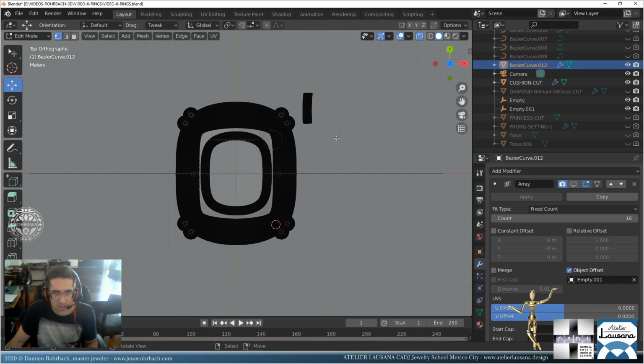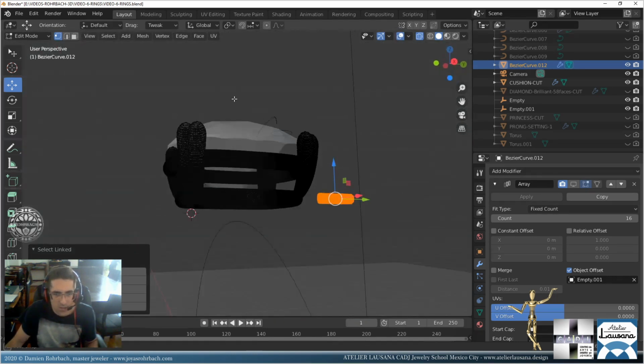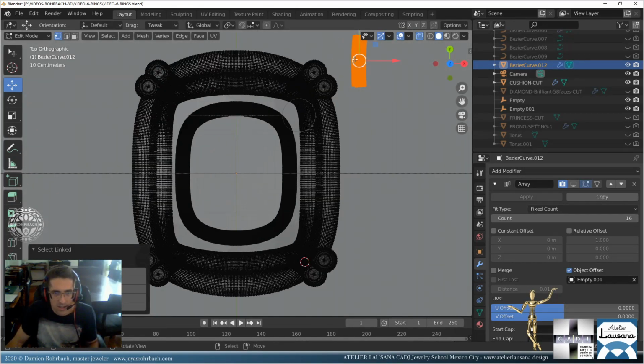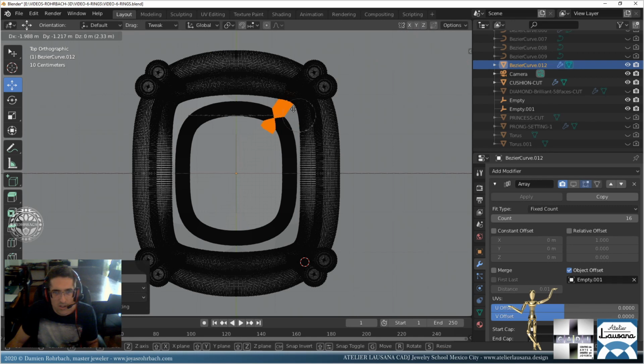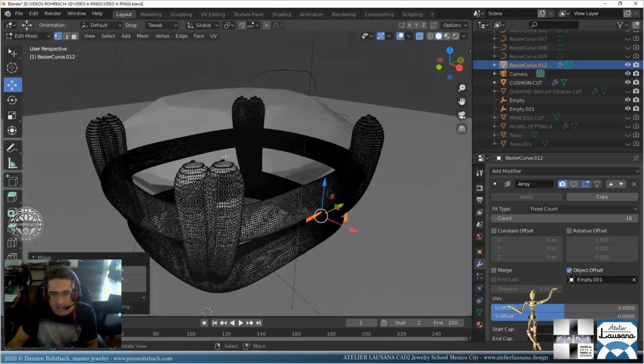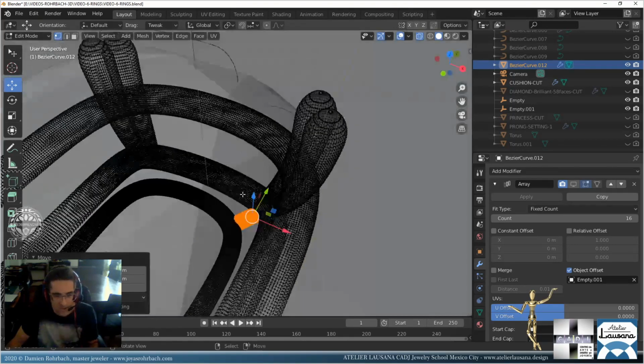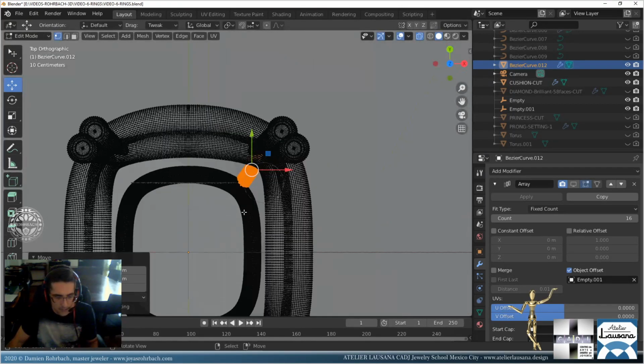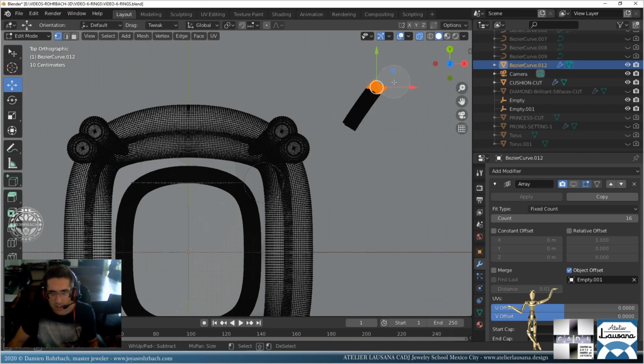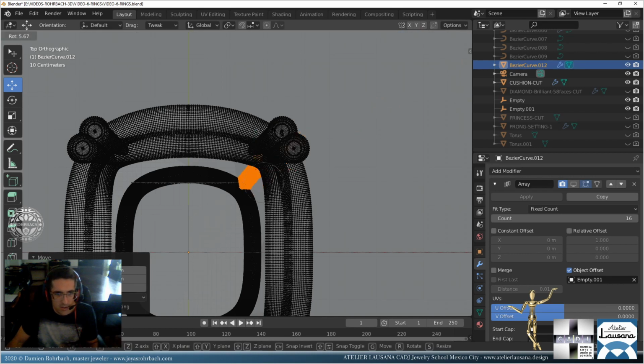Now delete vertices, the L key on the object, and let's rotate this with the R key. Let's move it right here. Let me see. Okay, it's too big, let's make it smaller and put it into place. It's just a bit too long, so let's go out again. Alt A, C. Let's cut it a bit more here. Delete vertices, L. Let's make it a bit fatter here, and rotate a bit more.